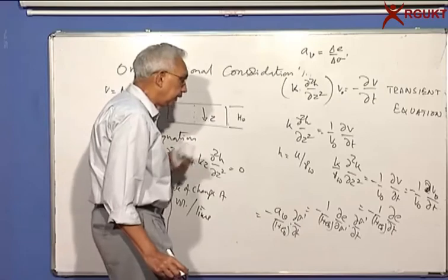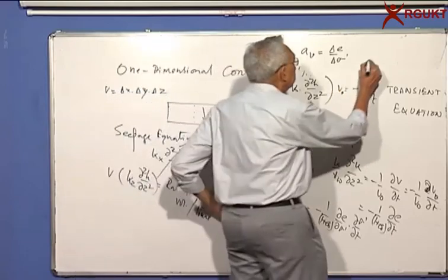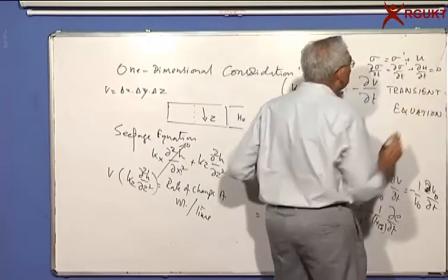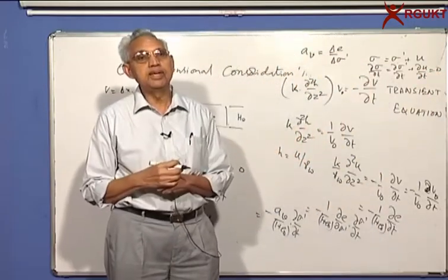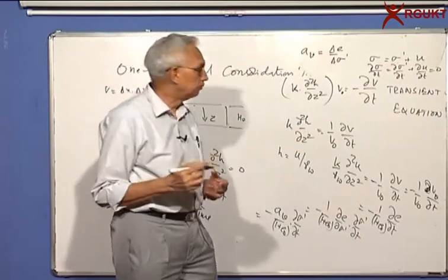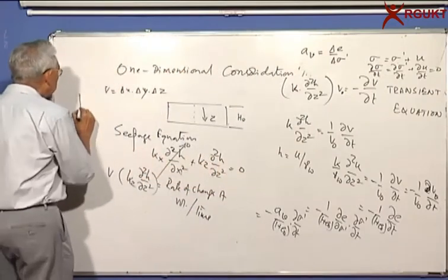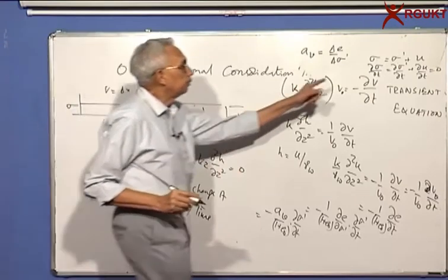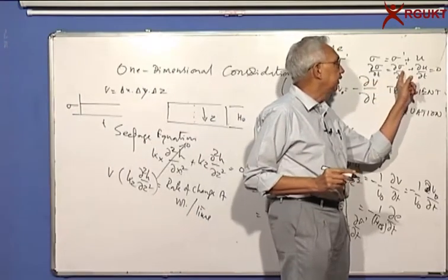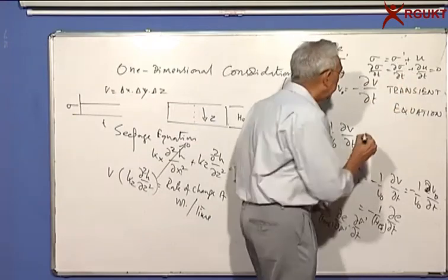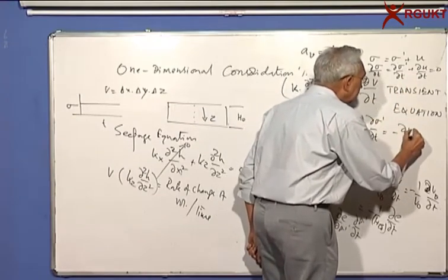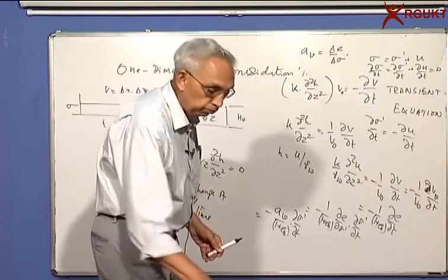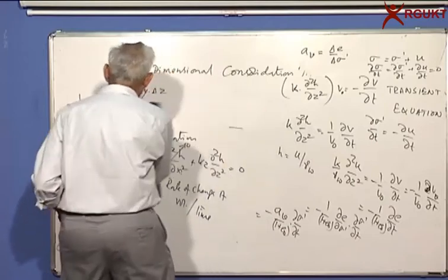Now you also have the effective stress principle, which means sigma is equal to sigma prime plus u. Can I differentiate this equation? Does the applied total stress vary with time? We said it's a monotonic loading under constant loading, sigma t. So delta sigma by delta t is 0. So can I say delta sigma prime by delta t is equal to minus delta u by delta t. And once you substitute that here, we get the basic consolidation equation,